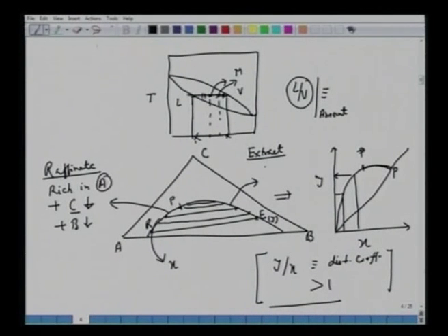That also contains A, B, and C, except it has a larger amount of solvent, closer to this apex. So a large amount of solvent, C is larger. This is closer to C than this point. So on any tie line, this is closer than this. Y is greater than X, except beyond this plait point, where the slope starts decreasing. Slowly and slowly, beyond this P, the slope decreases. So it's closer towards C here.